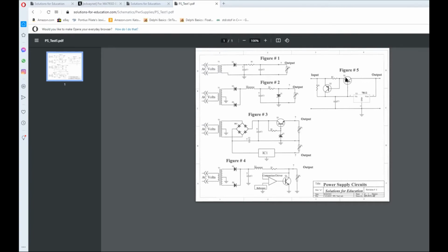And this bias voltage says to this guy, hey, get in here and help out. This is your power steering module, if you will. So this guy here conducts more, and this guy can be heavy enough to cover 3, 4, 5 amps. Well, this 7812 can't do that. But if you've got a good enough transistor up here to carry 3, 4, 5 amps, he'll kick right in here and add in. Now, this is still the guy that's controlling. Now, let's say the current gets a little bit too much, and this guy says, I can handle up to maybe 3, 4, 5 amps, but don't go pushing it beyond that.